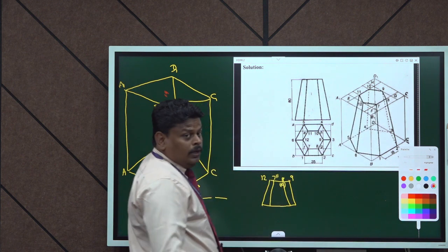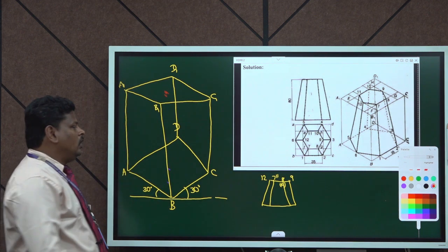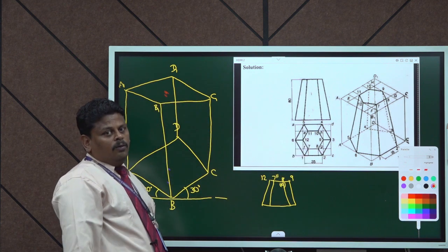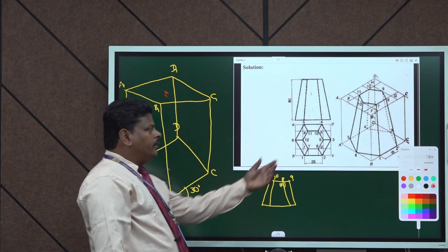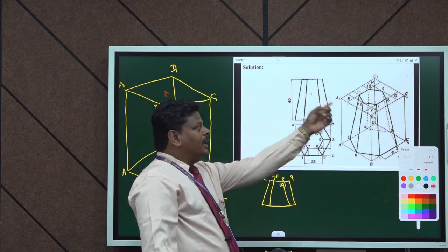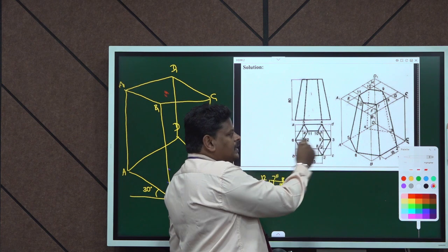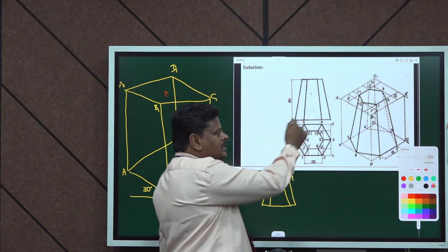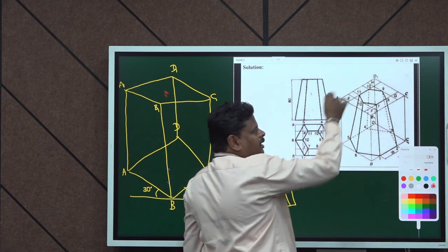We draw all these horizontal and vertical projection lines only to indicate all these cutting points 7, 8, 9, 10, 11, 12. We want to mark these cutting points in our isometric view. For doing that, we transfer the accurate location of these cutting points into our isometric view. When we draw horizontal and vertical projection lines in our box ABCD, we transfer the same to A1, B1, C1, D1.